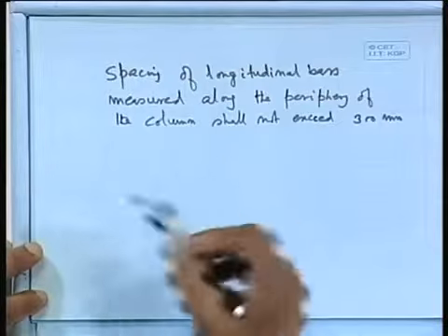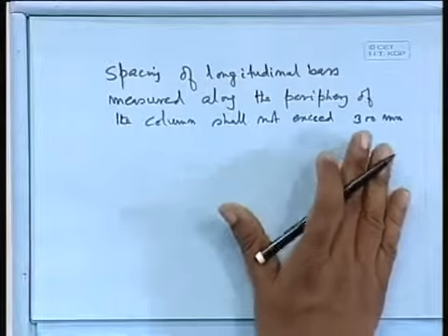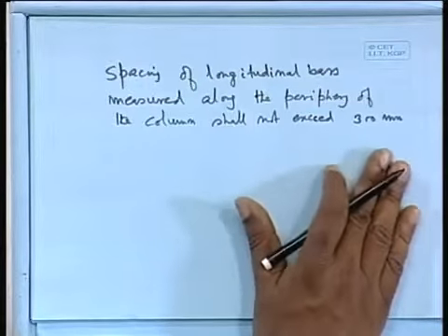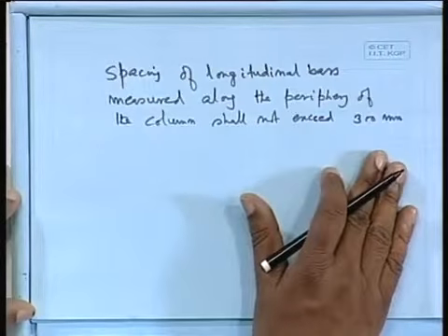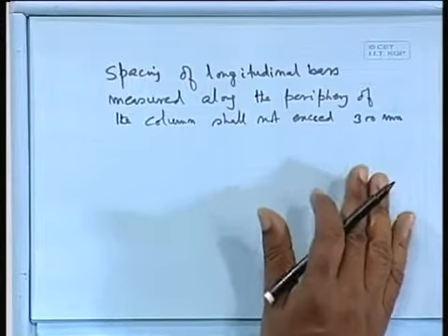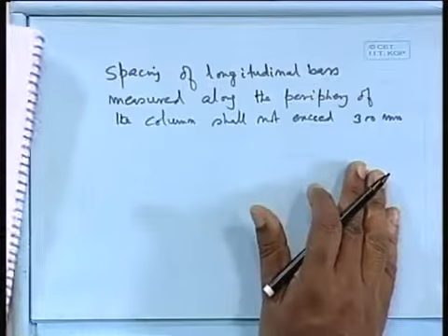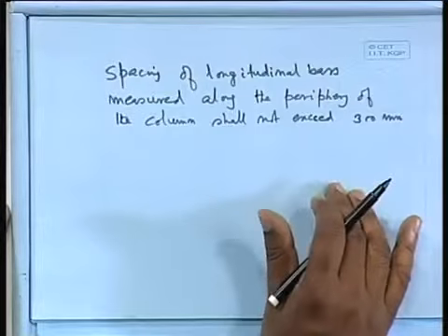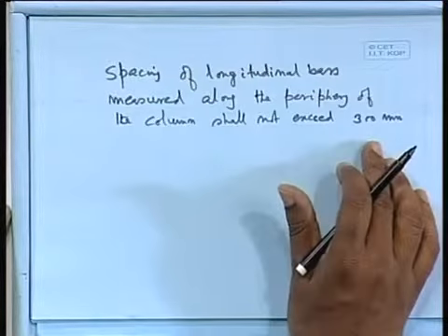Even if you say reinforcement, what I mean to say is it is not dependent only on the strength point of view, the load applied. It is dependent on so many other guidelines also: the minimum number of bars, then bar diameter, then this restriction of 300 millimeter, all those things.